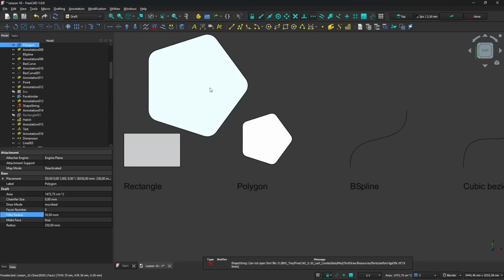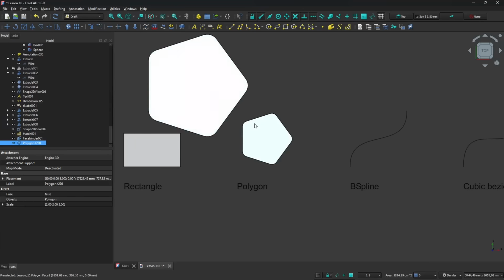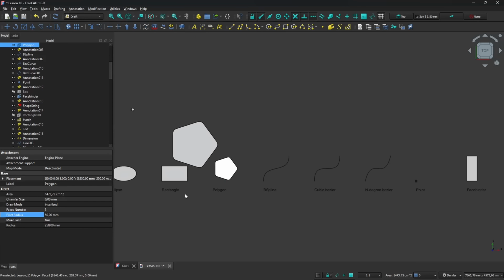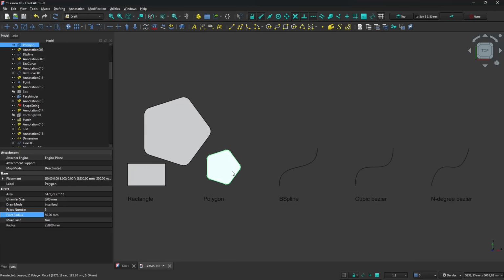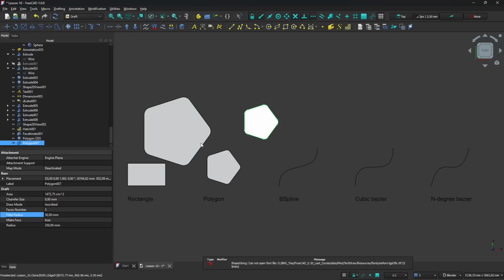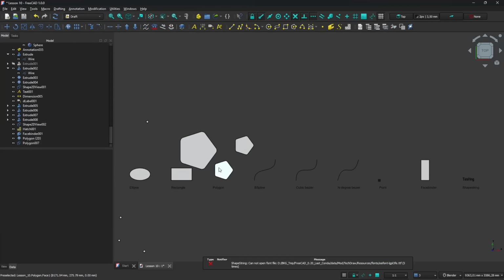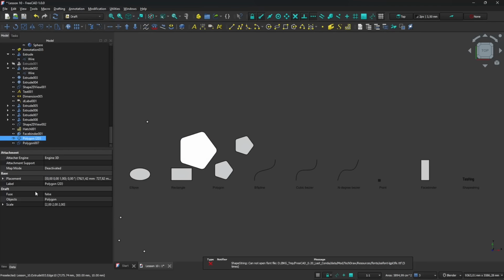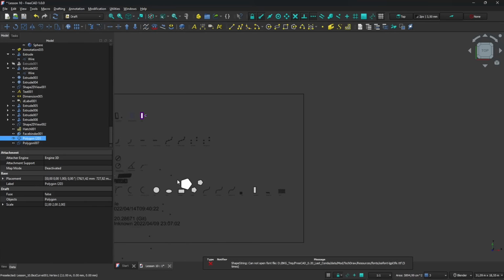This is why we want to use the clone, because we want to maintain a relation to the original instead of just copying the object. You can also move and copy if you activate the copy option here, so when you move it, you can copy simply like that. So the clone also gives us additional features.